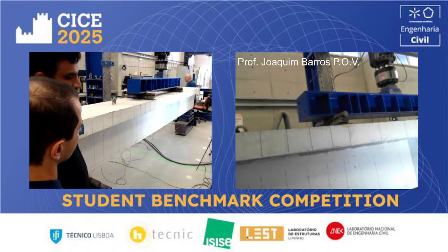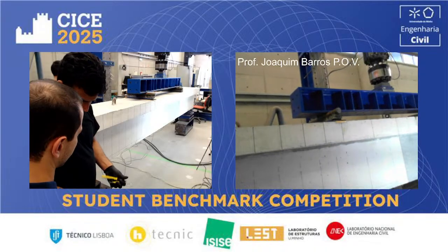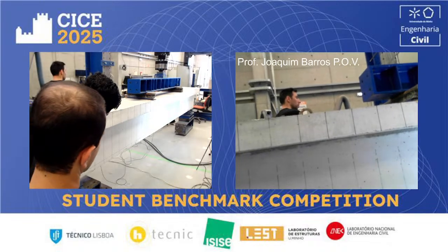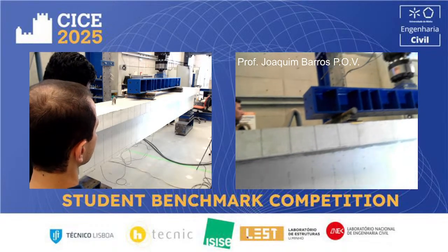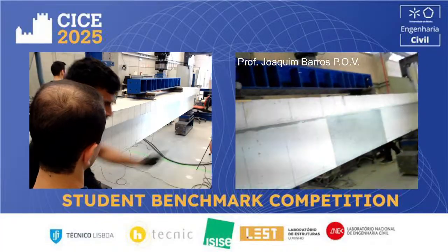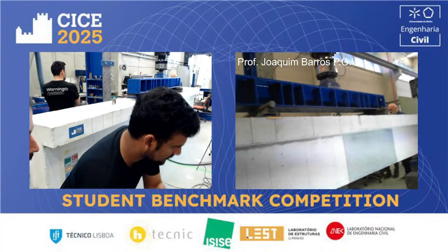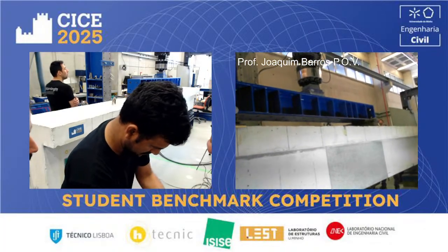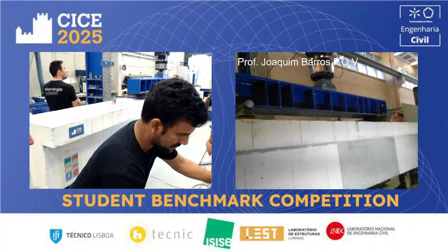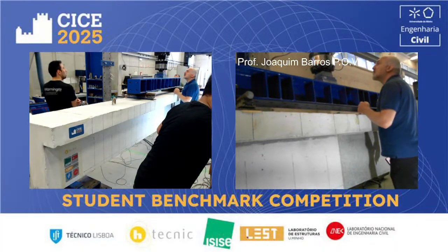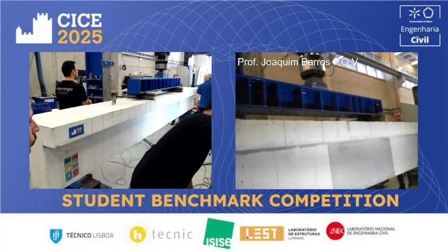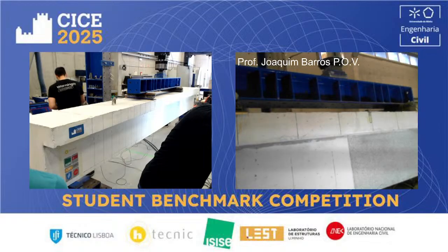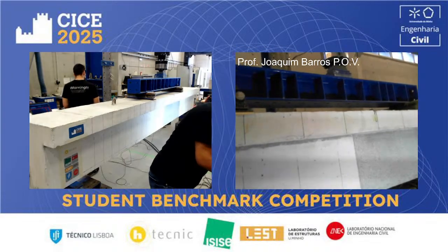So we have 3 laminates in the soffit of the beam, and these lines that we see here are in the alignment of the existing steel stirrups. This zone is the region that will be monitored by DIC, digital image correlation, to evaluate the maximum crack width in the cracks that will be formed in this region, as well as the average crack spacing.